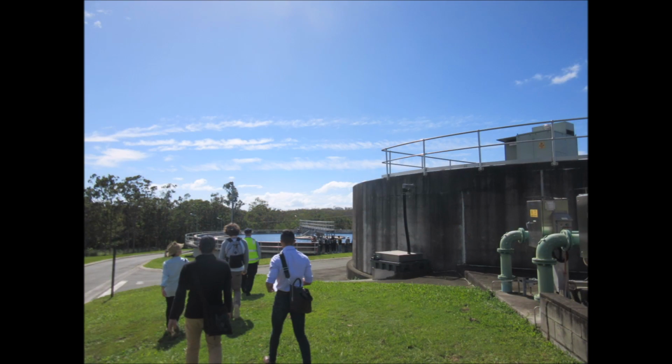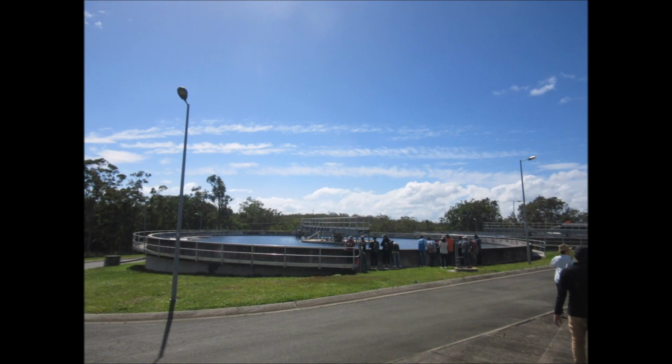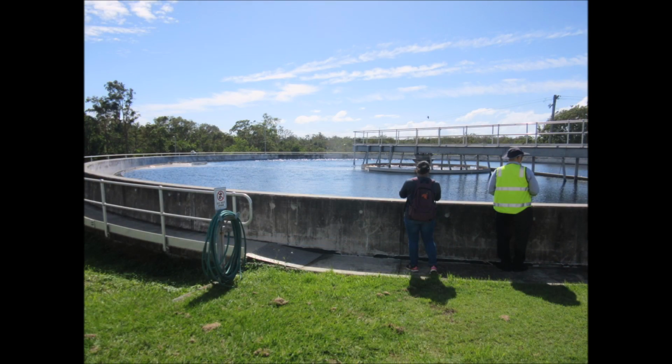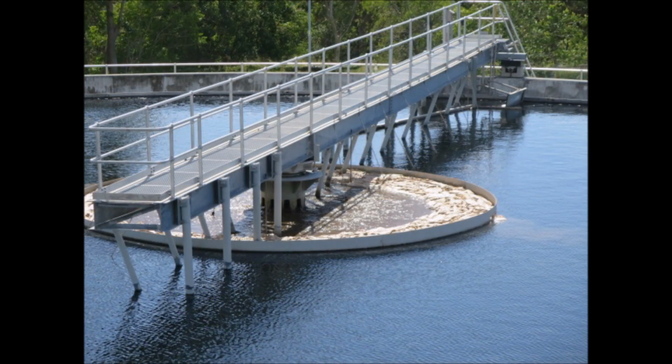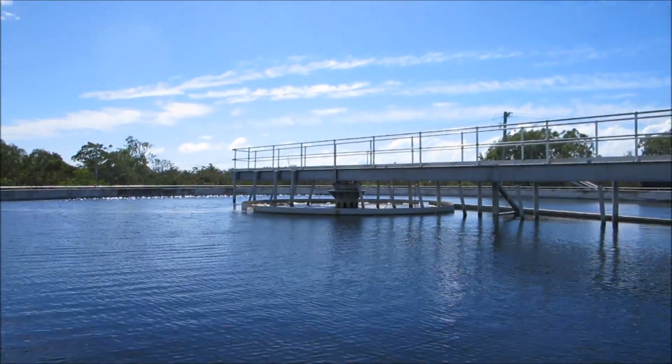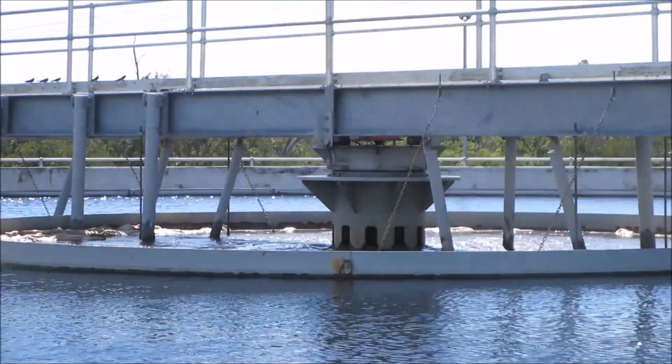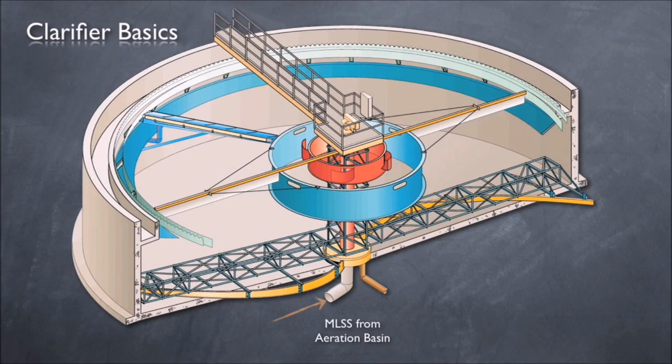The feed from the oxidation ditch is pumped through underground pipes and enters the clarifier through a centrally located feed pipe. To aid the settling process, alum, a coagulating agent, is added and mixed with the liquor before entry into the clarifier. There are 2 outlet streams in the clarifier: the activated sludge stream, which is composed of the return activated sludge stream, which is recycled back into the bioreactor, and the waste activated sludge stream, which continues onto the dewatering process. The second stream is clear water effluent, which flows over the clarifier.